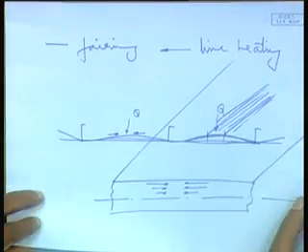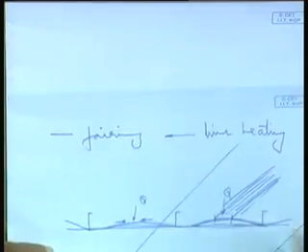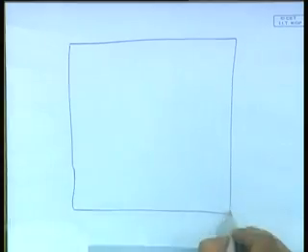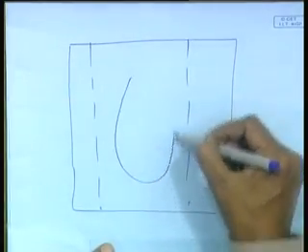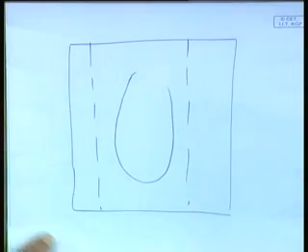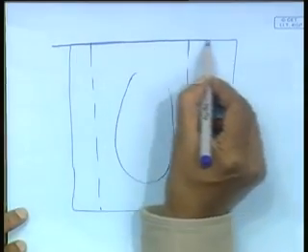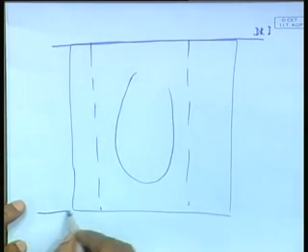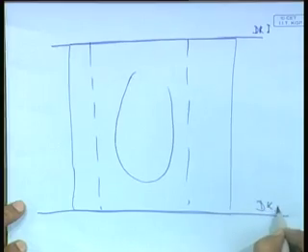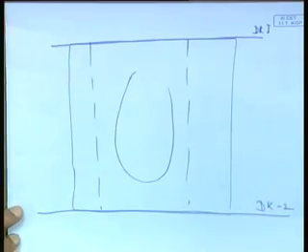Now we will not go into the detail of this. There are various ways it is done, through spot heating, or a combination. Suppose this is your panel, this is one stiffener, this is another stiffener, and this part has buckled. Say a flat panel is welded to a deck, deck number 1, and welded to another deck, deck number 2.